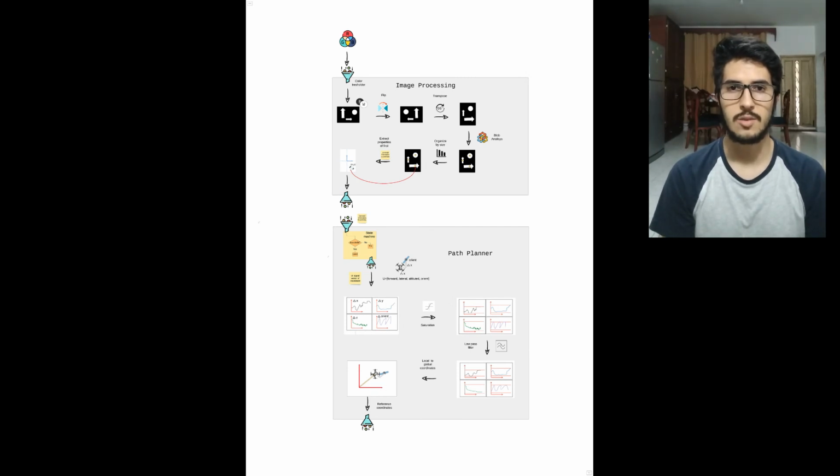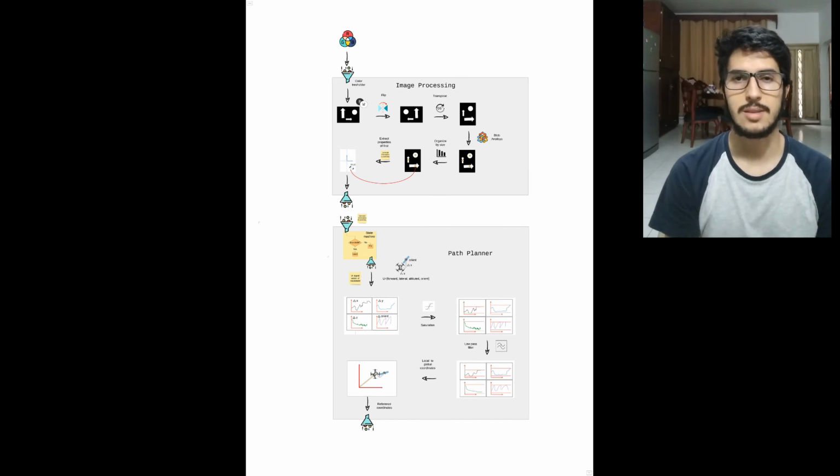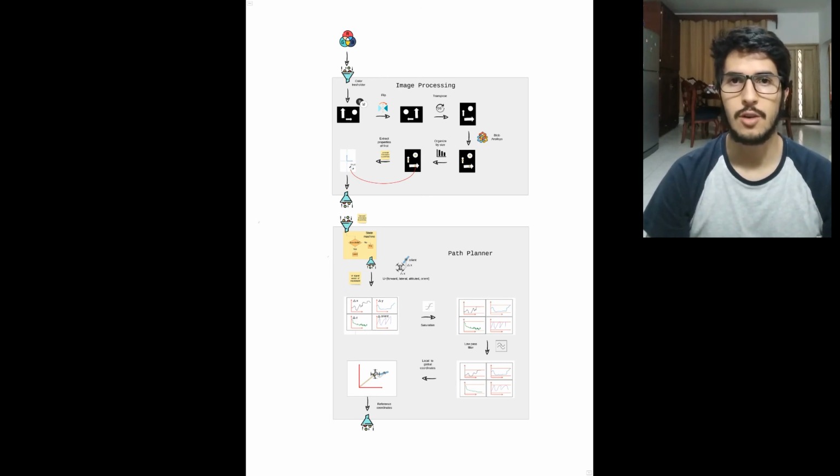One of the main things we learned is to identify shapes in the image taken by the drone and then process them and decide on a course of action with respect to what has been identified. One of the main challenges we faced was to reduce the simulation computational cost in order to avoid a saturation in the execution when we use the real drone. So we switched from using some of our own functions to using Simulink provided blocks, which brought us a significant improvement in this cost.